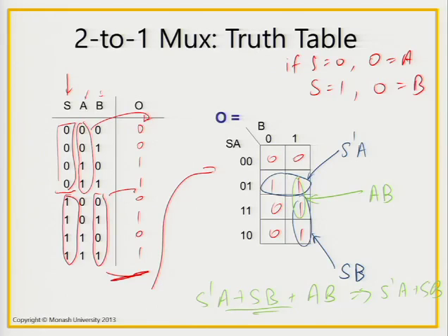Now, it's a little bit unclear how you would go from this one to this one, and that is one of the disadvantages of using Boolean algebra by itself. And that is really why we like using Karnaugh maps, because you can see visually that I don't need this green one because, oops, I need that one. I don't need the other green one, AB, because all the 1s are already covered, and AB is just redundant.